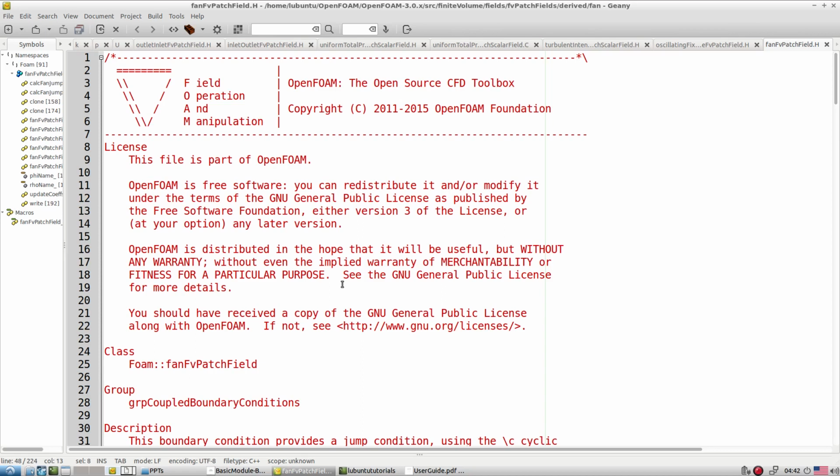But let's say even with that you are not able to simulate your own case, then we have to go towards our own boundary condition development. Let's say we want to specify an oscillating parabolic condition on the pipe. That condition is really not available, so either you go with groovy BC options, where you use groovy BC and try to create that condition, or you can code your own condition from scratch. We will explore both when we move towards the advanced options.